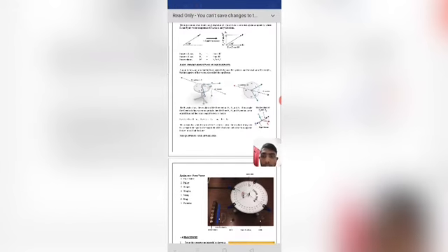If you make the R vector a zero magnitude, then F1, F2 and F3 vectors are in equilibrium and their sum is equal to 0, as shown: F1 plus F2 plus F3 equals 0, or F1 plus F2 equals negative F3, or R equals negative F3.